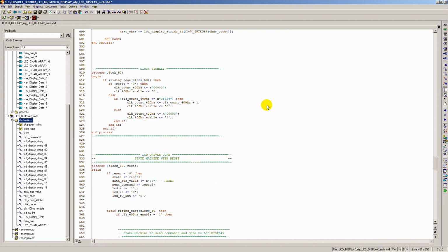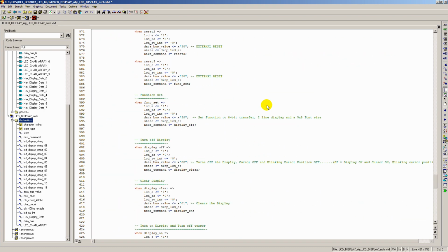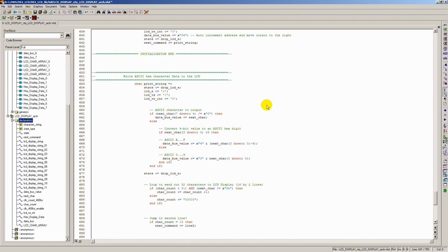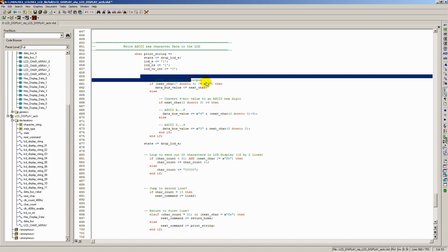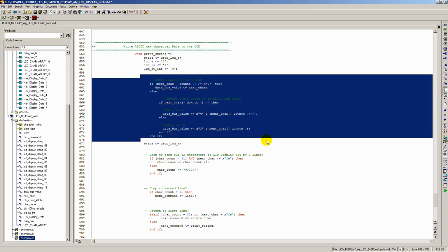So now we'll go back down to our area there where I was declaring that, where we're actually sending the hexadecimal value. So that's what this area of code is doing, essentially dictating how those particular input switches that we have are going to react.